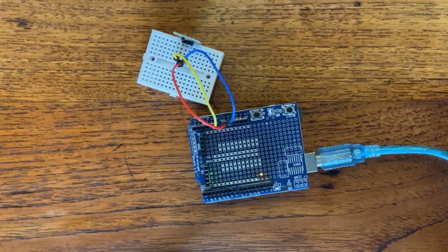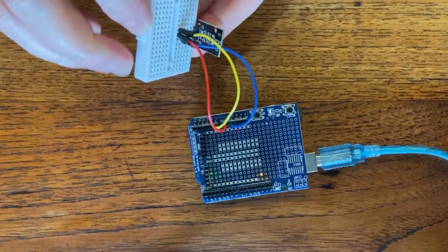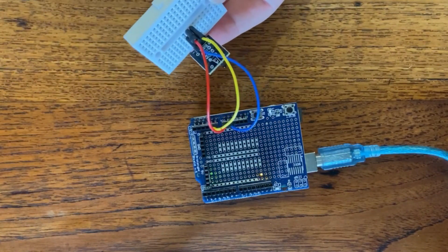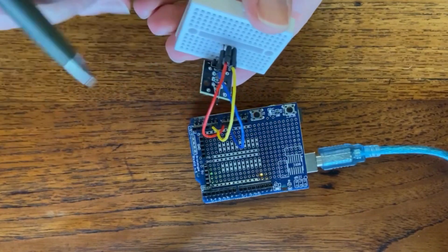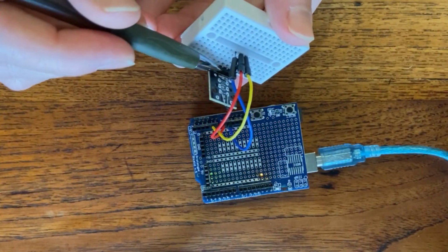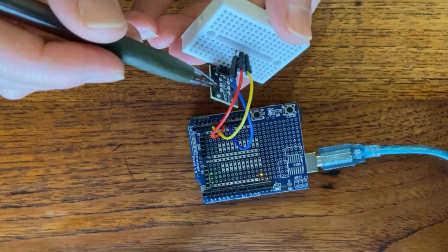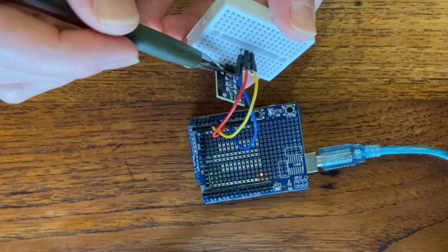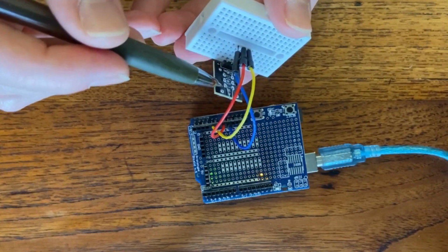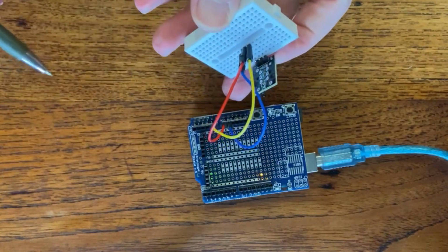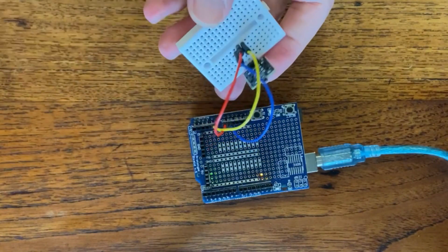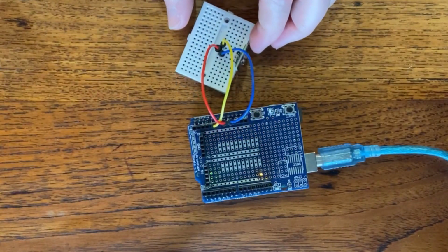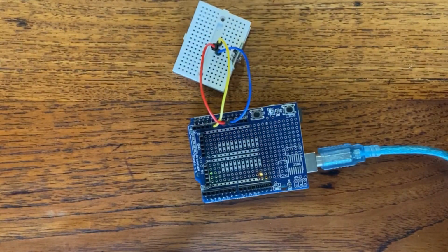It's simple. It has got the resistor for the current limiting, the bias resistor for the NTC thermistor, mounted on the board. You don't need an external one. It's a 10k resistor.